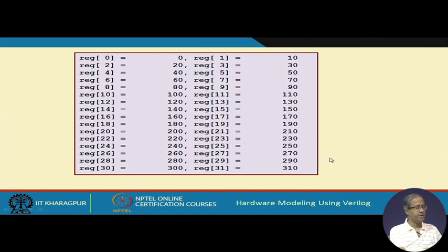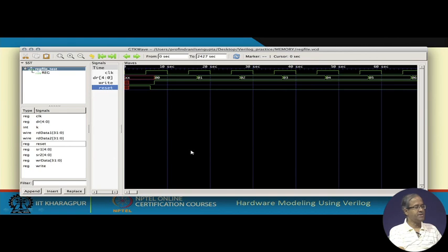Okay. Now, if you also see the timing diagram, I am showing you 2 parts of the timing diagram. This is the first part where reset has been activated, initially reset has been activated, and then you are writing the data 10 into k. You see the register number dr is changing 00, 01, 02, 03. So, the write is continuously active because it is going low and immediately going high. So, that you are not seeing here, write is continuously active. So, 0, 1, 2 with the clock edge writing is going on.